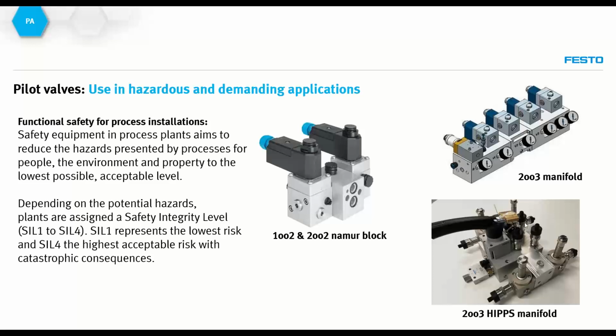These pressure transmitters can be connected to the DCS system to have an active reading of the functioning of the solenoid valves within the design, so based on the performance we can see how well the system is working. These are mainly done for very demanding applications where we have a single air supply and need to actuate one single actuator, but with an extremely high reliability.